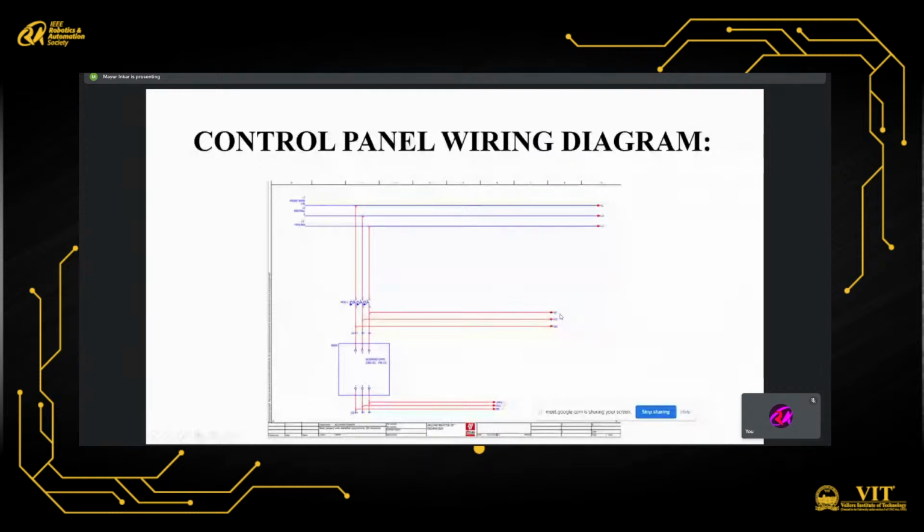Okay, so this wire numbering shows that on the next page of this drawing there will be another electrical device, and that electrical device may be getting connection through these wires. These wire numbers will be available on each and every wire on the sheet of your drawing. So by watching that wire and wire number, you can understand from where this connection is coming and how your component is getting the electricity or the voltage it needs to work.